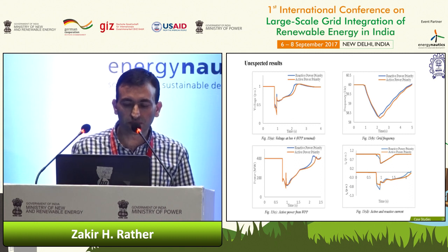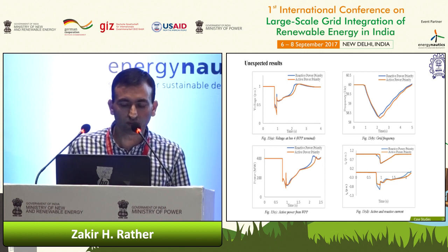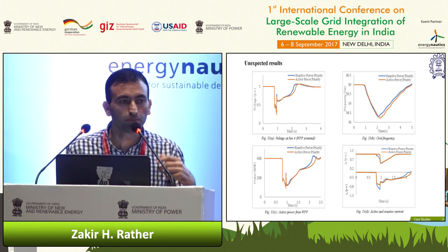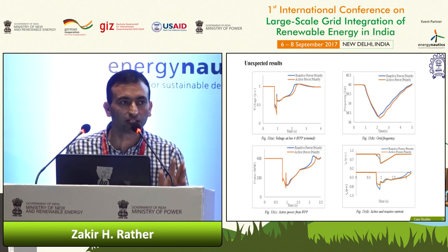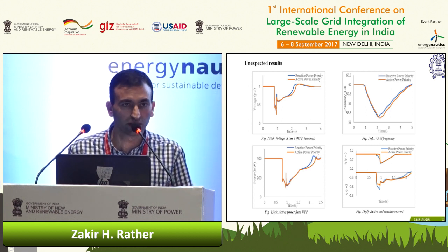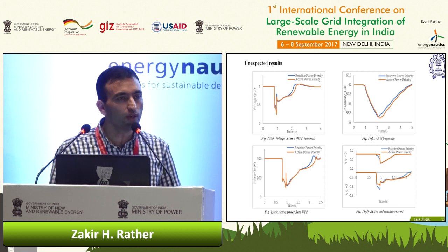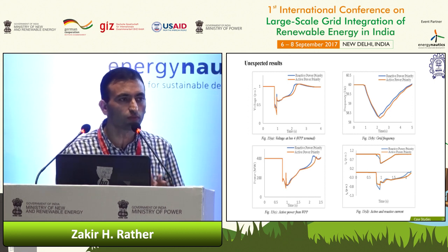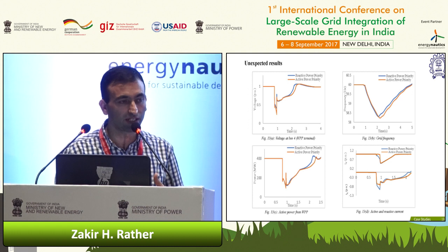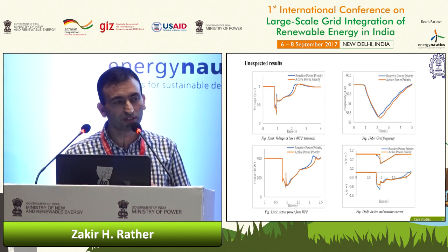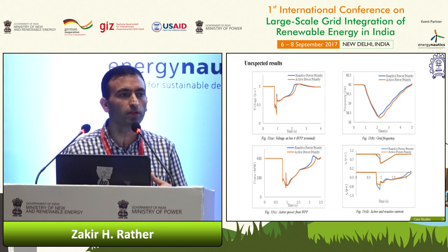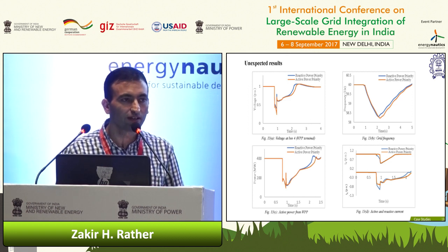In this case, because active power injection depends on voltage and current, it is the product of voltage and the active current that is being injected in the grid. So it is a product of two quantities, voltage and active current. Now if we have a predominant increase in voltage compared to the decrease in current, then we can probably have more active power injection. And the reverse is also true.